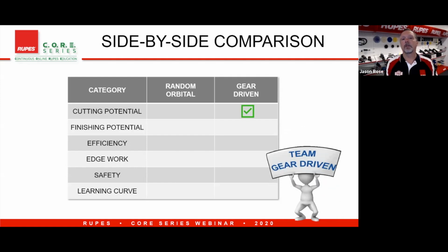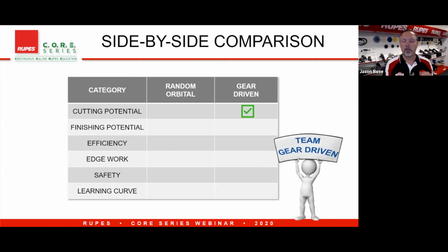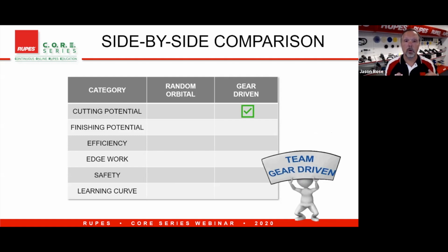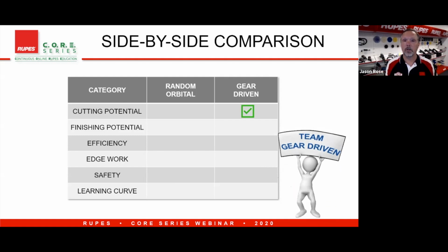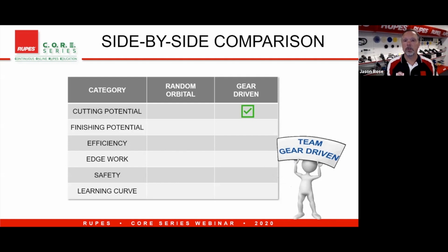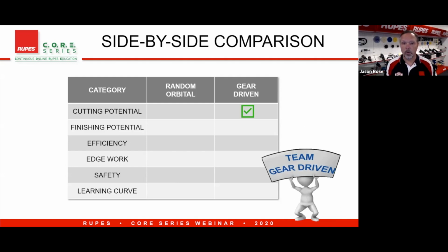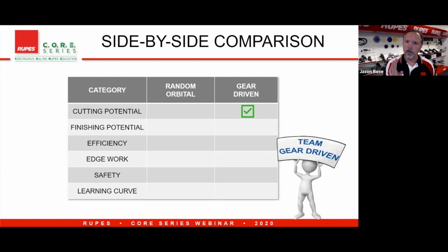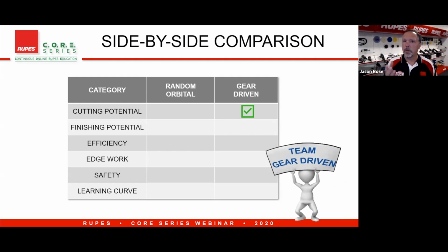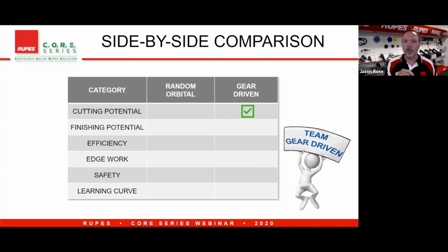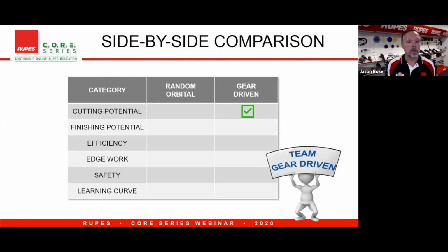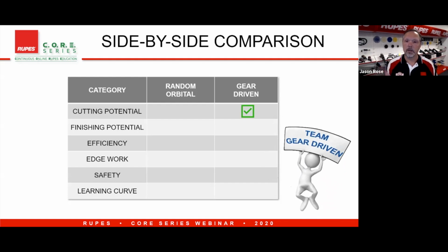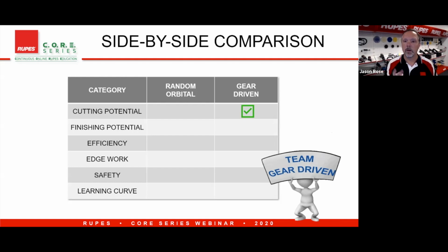Once again, we have to say, random-orbital has extremely strong cutting power, but it is a variable based on your experience and your skills with using a large-orbit random-orbital tool like BigFoot. The comments that you might have heard or said about random-orbital just being a finishing tool are simply not factually correct. It is not correct. Crazy cutting tool. Both of these are cutters.